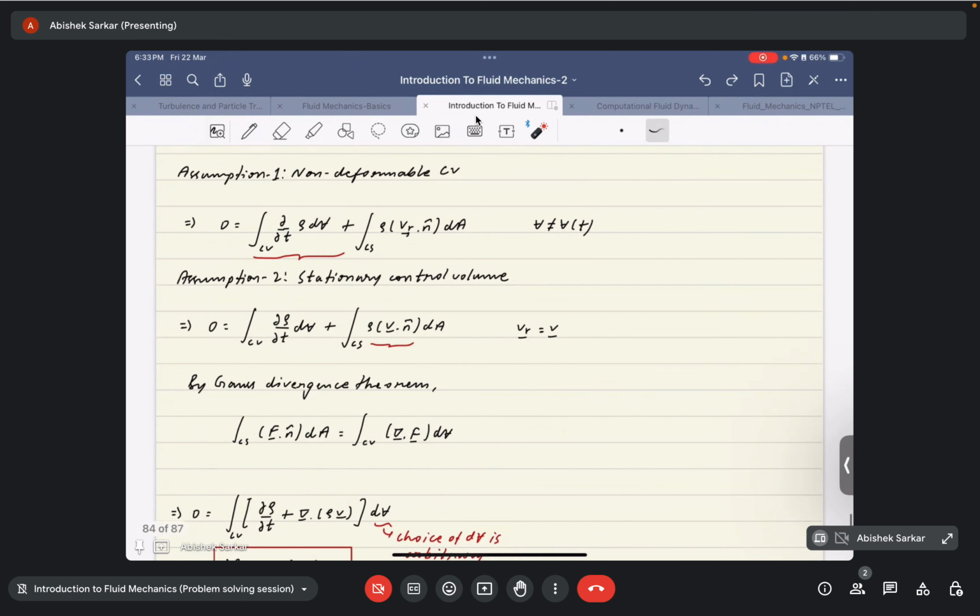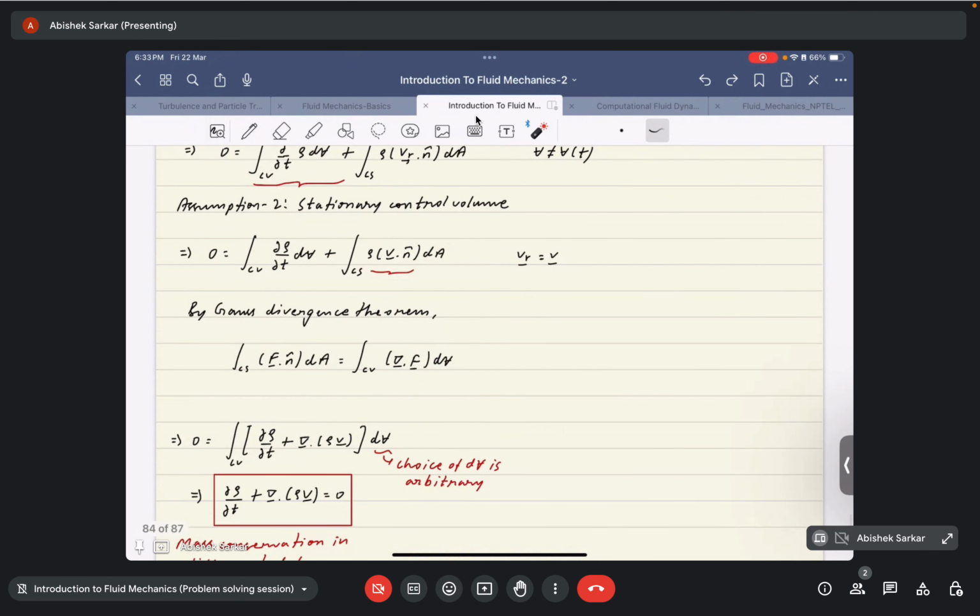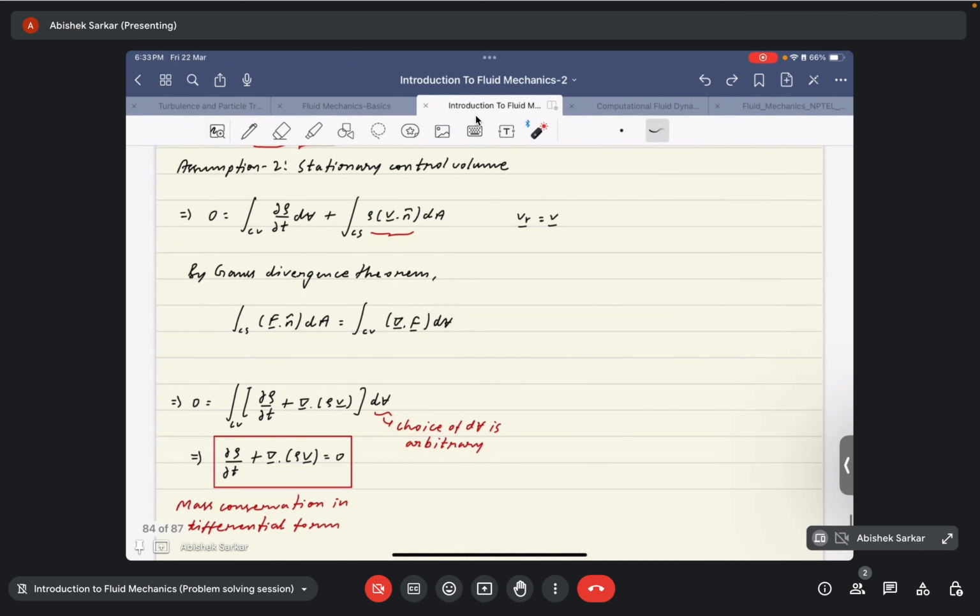Then by applying the Gauss divergence theorem in this term, we can convert this surface integral to a volume integral. And once we do that, we can club together all these terms, because they both are a volume integral over the same control volume. So we can write the volume integral of dou rho by dt plus the divergence of rho V over a particular control volume is equal to 0.